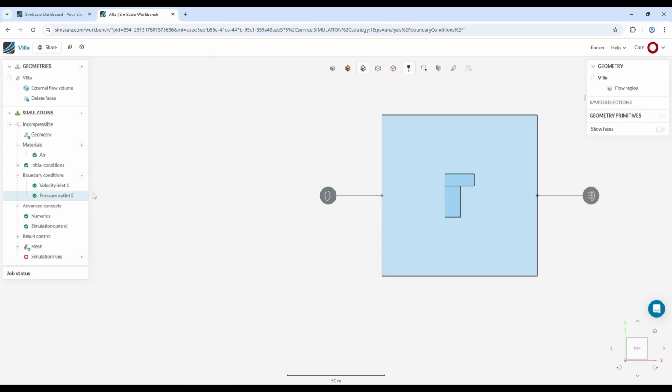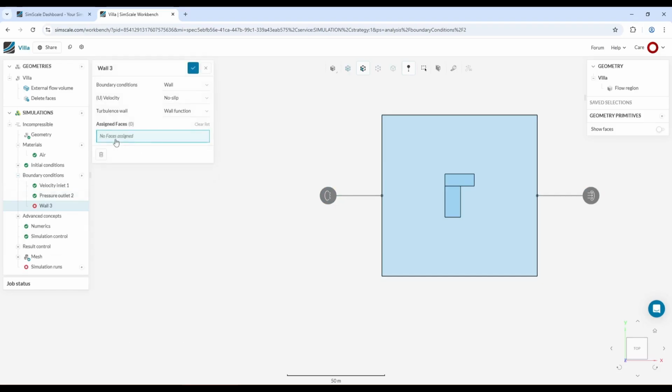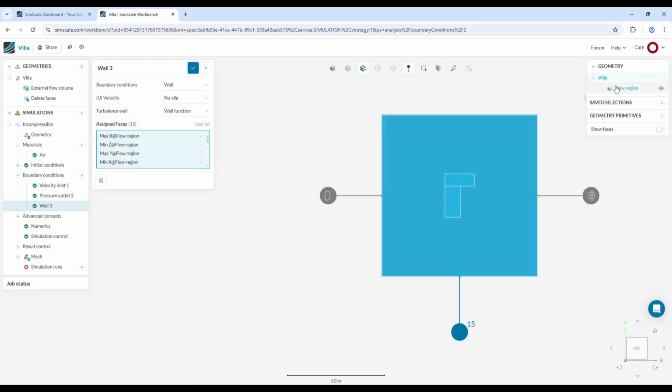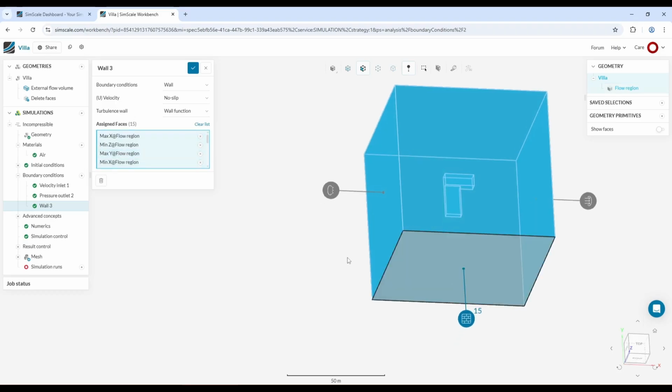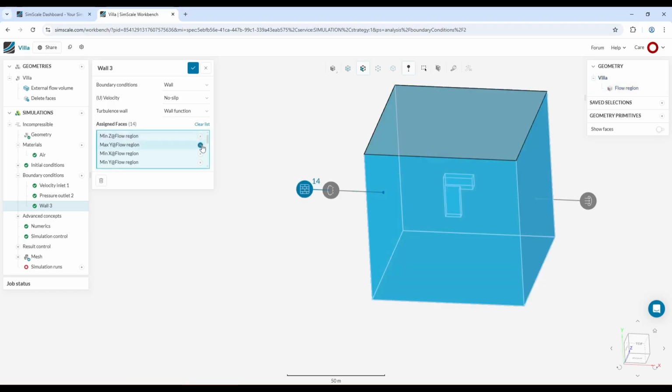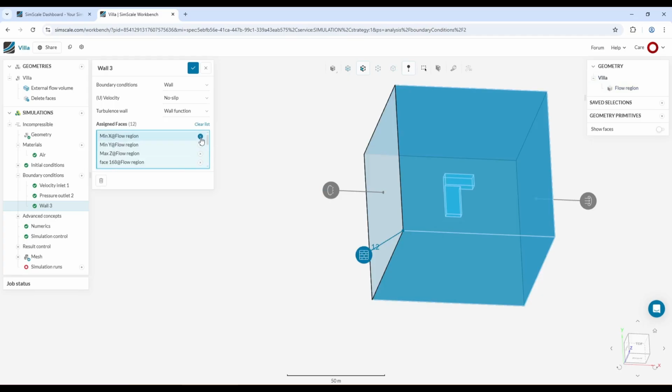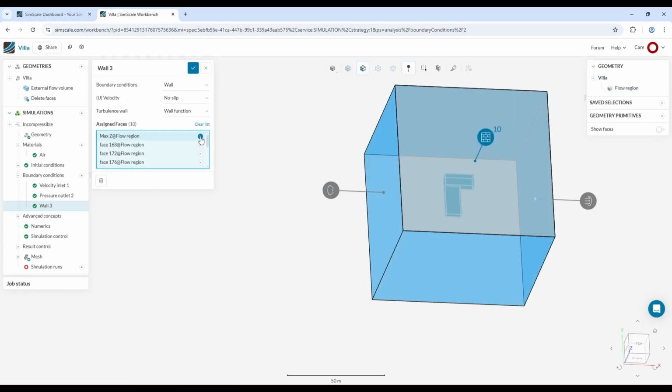The ground and building are also represented as walls, so there are obstacles for the flow of the air. Here we should remove all the edges, all the surfaces that are defined as where the air is coming and leaving from this area. So only walls are the obstacles that should remain in here. As you can see, there are 9 surfaces inside this box that are defined as well.